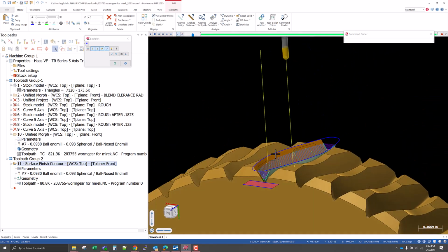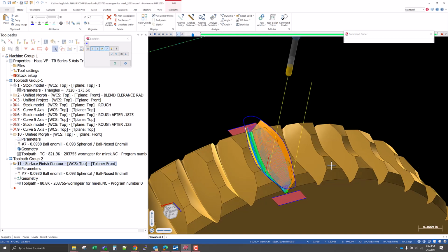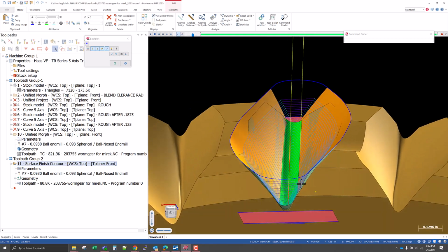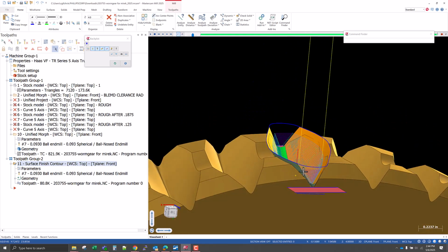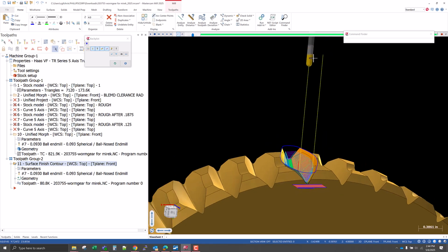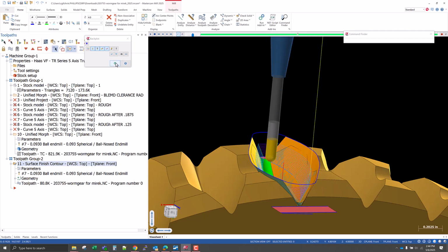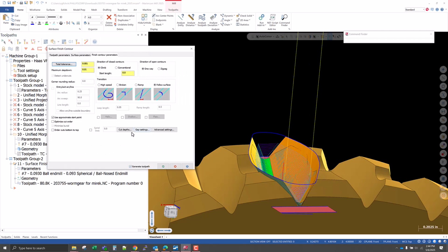Okay, so this very clearly demonstrates what I think of as a superior toolpath. A superior toolpath really to me is any toolpath where in a single toolpath, you've designed the tool motion to give you one entry point at the start and one exit point at the end, and the tool has kind of stayed down using the style of motion you want.